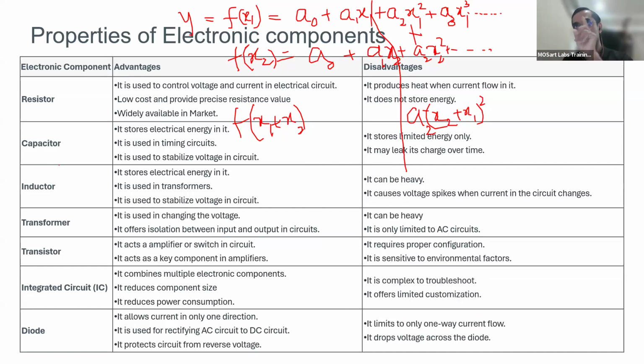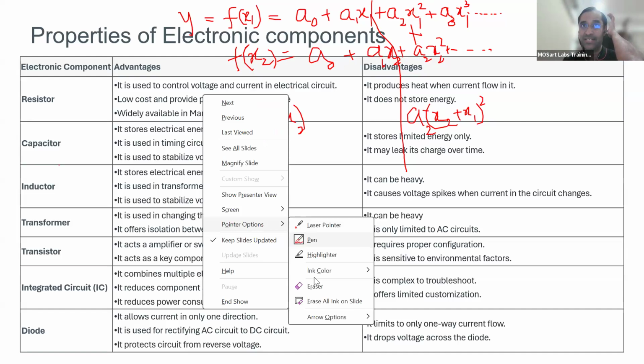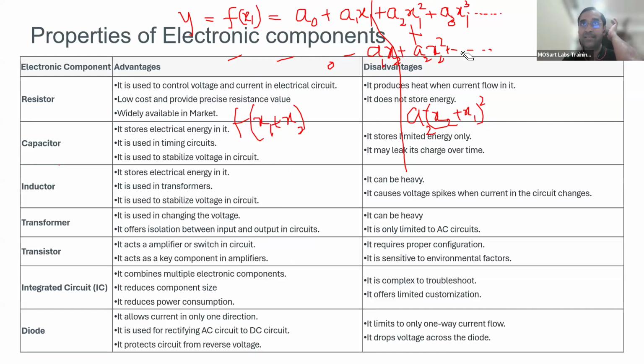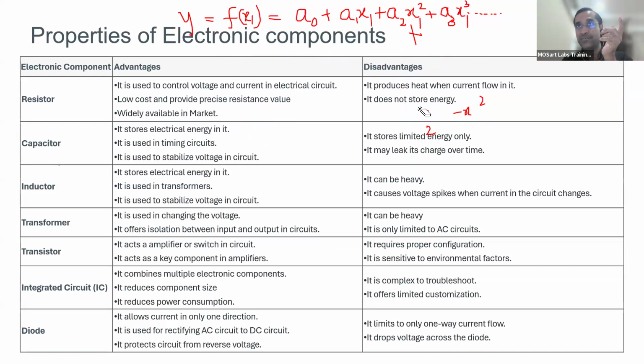And so Jaskaran, when you're talking about power amplifiers, you talk about linearity of these power amplifiers, linearity of your audio amplifier, and this is how the linearity is also modeled. Your third order harmonic or second order harmonic, whichever comes in this, the harmonic distortion, this is nothing but this. Okay. Now let's go one step further on this nonlinearity, and let's see this math is so powerful because it helps us to intuitively understand the physical phenomena.